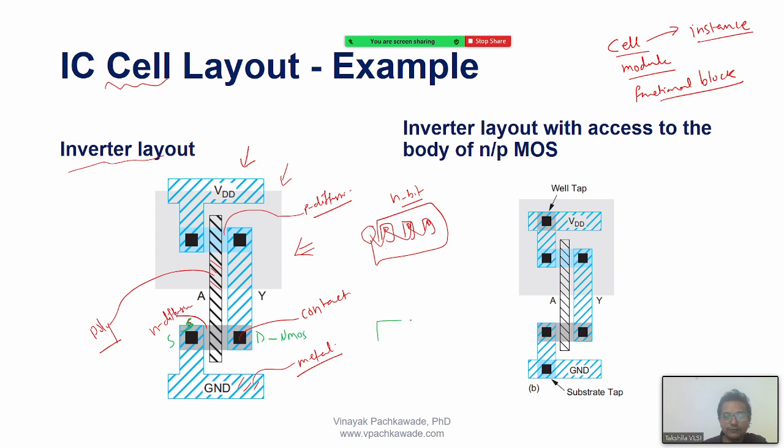So simply what I do is draw this diffusion area, and I know that here is my source, here is my drain, and they will be separated when I draw the polyline on top. As soon as I draw the polyline, by the technology the width of the poly is already set. So once I draw the polyline, I know that this is nothing but the channel length.